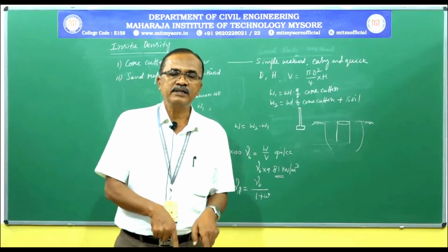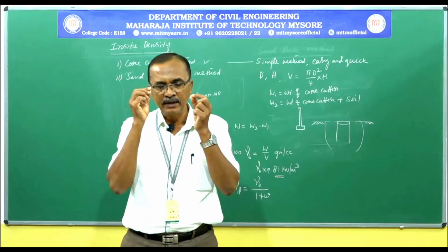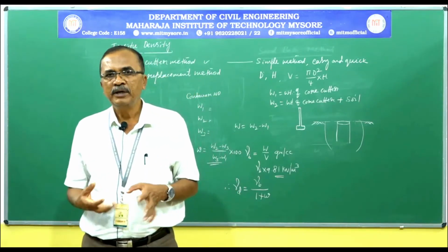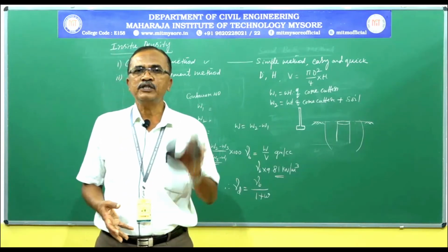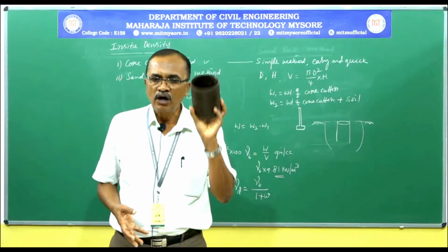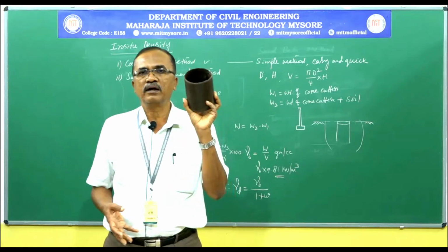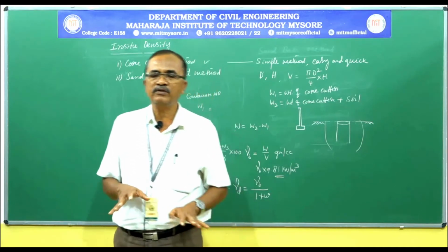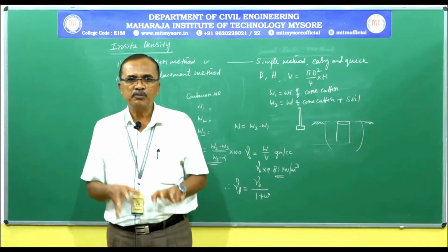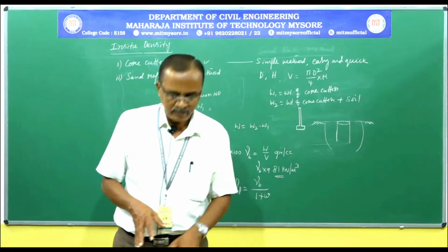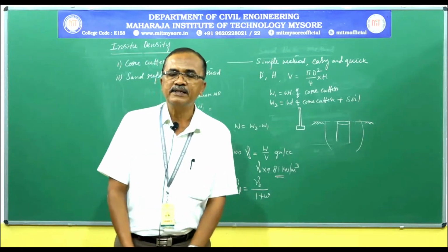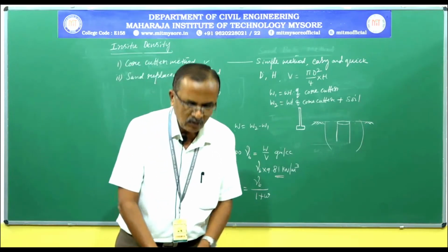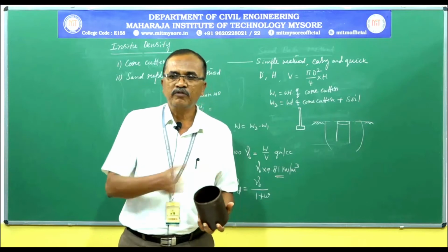Though it is a fine grained soil and the soil particles are sticking with each other, if there is presence of boulders, the core cutter method is suitable only for soft cohesive soil or clay soil, where we can comfortably drive the core cutter into the soil without much problem and which does not damage the core cutter. At the same time, if you remove the core cutter along with soil, we can easily obtain the core cutter with soil to perform the experiment.